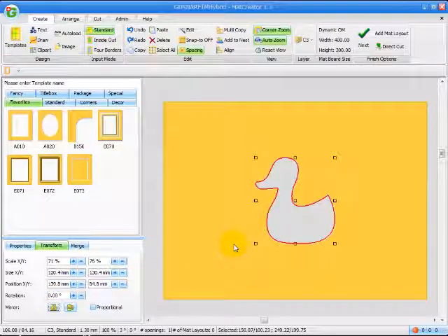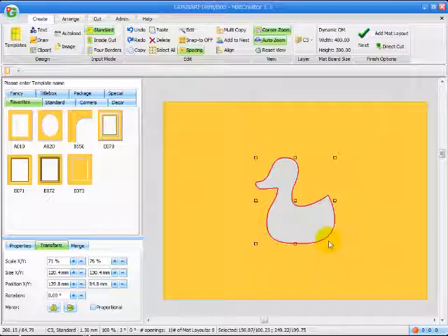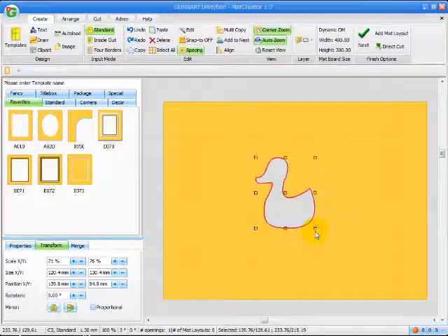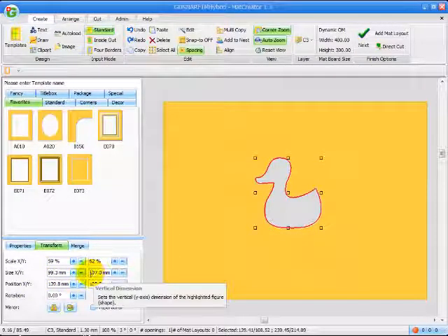Also, just one more little trick you may find useful for changing the sizes of clip arts is the control left click feature for the dynamic shape sizing. So if I put my finger on the control button and then move to any one of these points with the mouse, if I left click, hold the left click down and move, click and drag, you will see I can also dynamically change the size of a shape as well. And that also gives you the new shape sizes here in the size horizontal and vertical transform menu option display as well. So there's an overview of the transform tools available in GMC software.